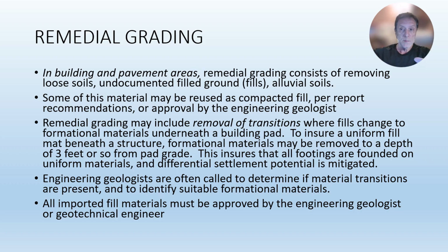And then as you go across the pad, you may have fill material on the downhill or lower part of the pad that sits on the downslope side of the hill. So that means you've created a transition from formation to fill, and you have a line going through maybe the middle of the pad. So you have, let's say, sandstone on the uphill side and fill on the downhill side.